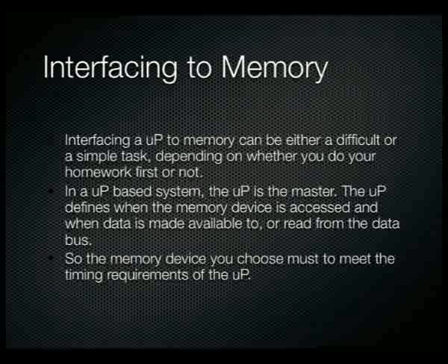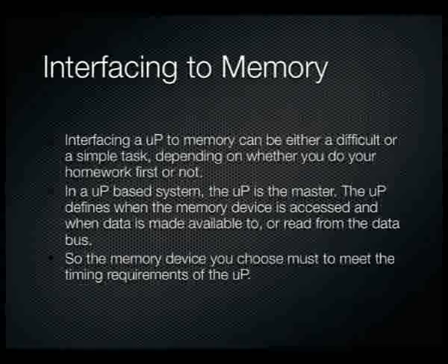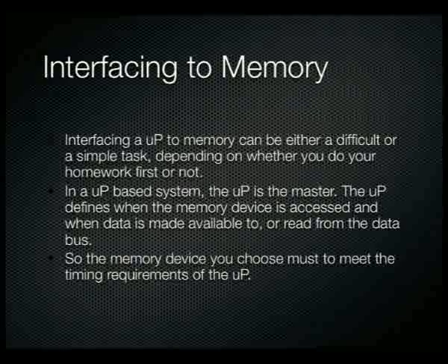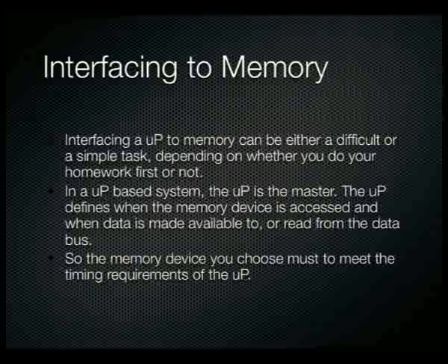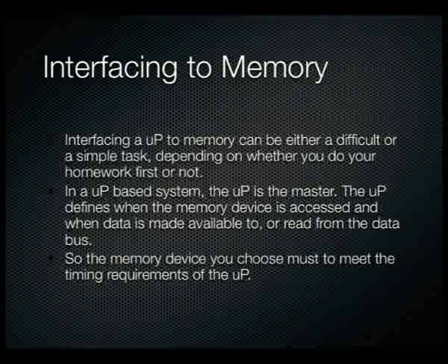In a microprocessor-based system, the microprocessor is the master. It dictates everything as far as when things take place. It defines when the memory device is accessed, when data is made available to it, or when data is read from the data bus.